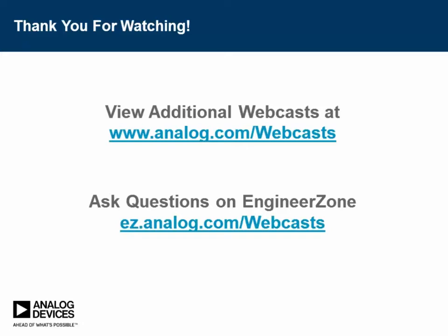Whereas when you're running the product and we say something's like 18 volts, if something's off in your system and it's really 18.5, you have now compromised the product. So we recommend that you stay a good amount away from the absolute max ratings. And in many new products, we're putting in something called max operating conditions, which is a number you can operate at safely.